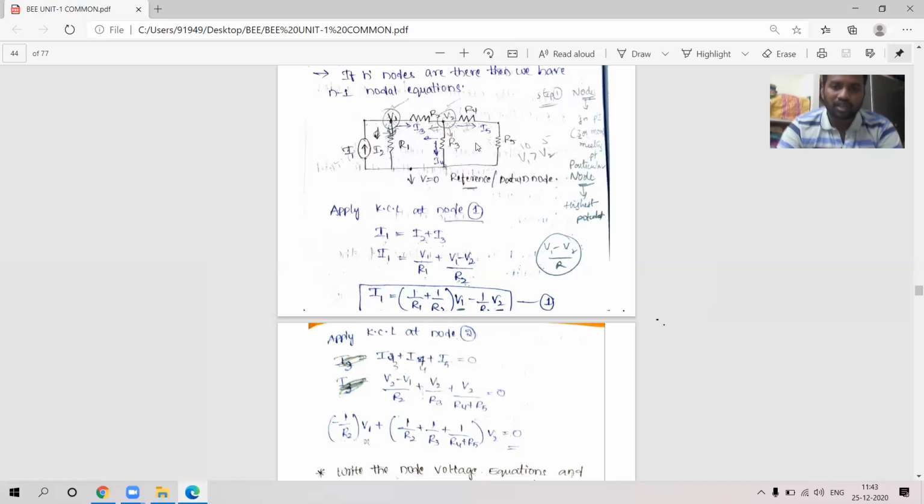If there are no current sources, what you have to do is replace it by Ohm's law, that is I is equal to V by R. What is V? V is nothing but potential difference. Potential difference means you will be having 2 points; difference means minimum 2. So I3, where is it going? From V2 to V1. So that's why I have written here I3 is replaced by V2 minus V1 by R2. Previously I had written V1 minus V2. Now I am writing V2 minus V1. Okay. So finally we can get V2 and V1 after knowing the voltages.